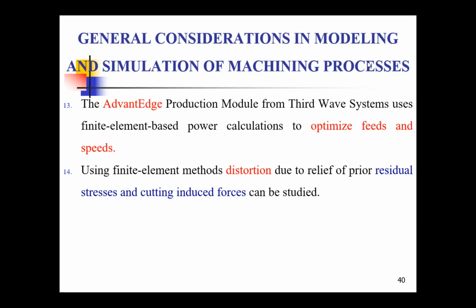So the dissociation of each and every element, because the total domain will be divided into finite elements. Why does the dissociation take place? Because of the residual stresses. Because we are going to have a shearing action, and because of the shearing action, some residual stresses will be there in the material, that is, in the individual element.